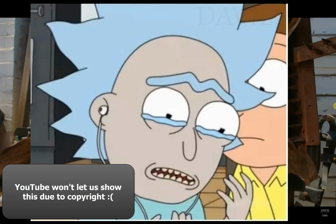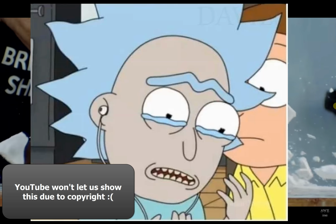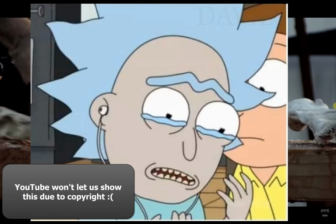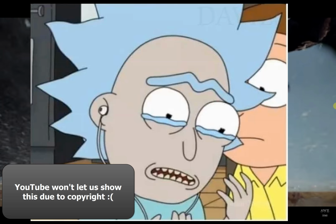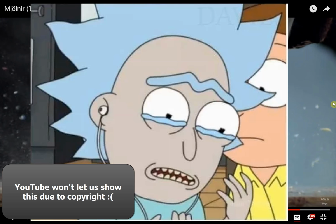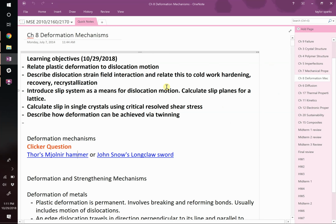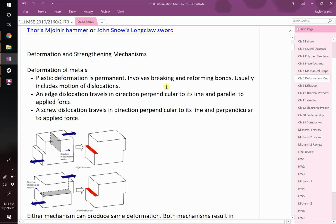So blacksmiths have been making things like swords and hammers and what have you for a very long time, but they didn't understand what was going on. It was only until like the 50s, 60s, thereabouts, that we started to understand why they do these different heat treatments, different quenching, why they can weld and join materials in different ways. We're going to be talking about some of that in today's class. A lot of it has to do with dislocations and how they move through materials, okay?